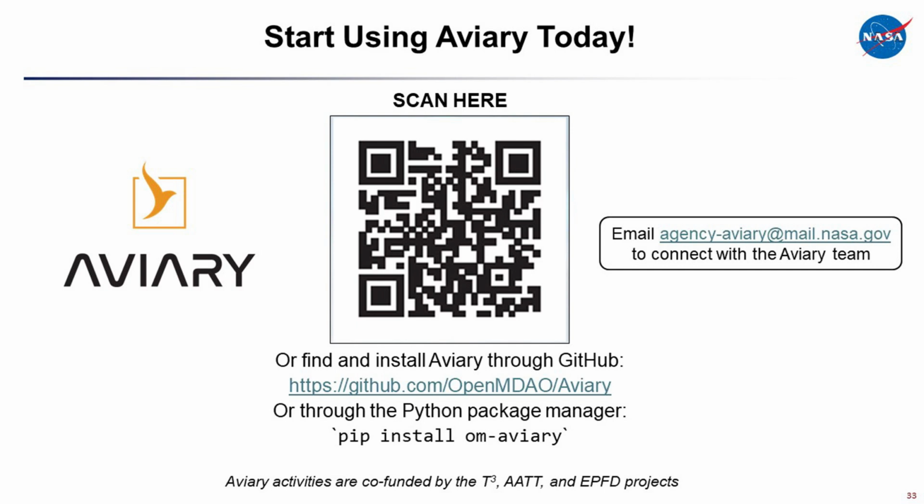And then on the aerodynamics side, they actually chose to take the geometry of the aircraft, run it through VSP Aero, and generate a drag polar. They just ran a series of cases, generated a drag polar, and then gave that to Aviary for mission analysis, where it would just interpolate on that table to save on computation time of not running it hundreds or thousands of times for every single point along the mission trajectory, every single iteration. You could also put it in the loop, of course. That's kind of how they used VSP Aero in that application.